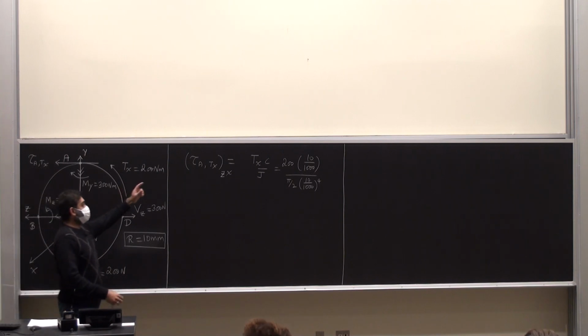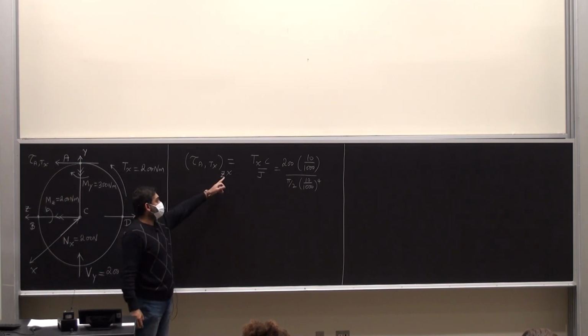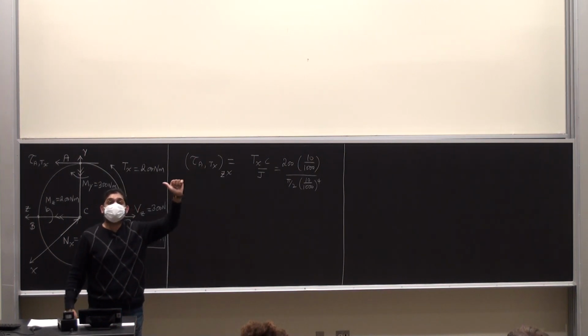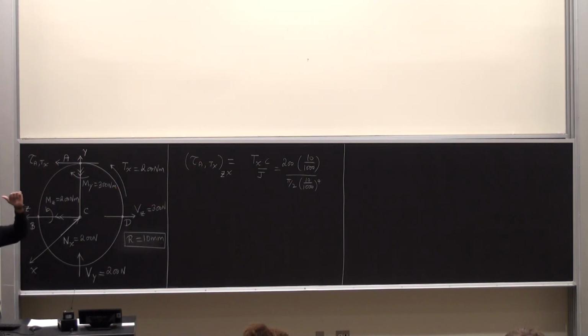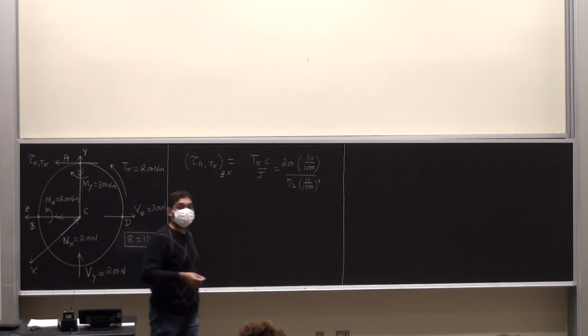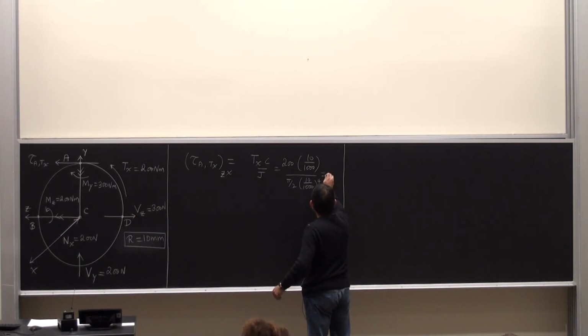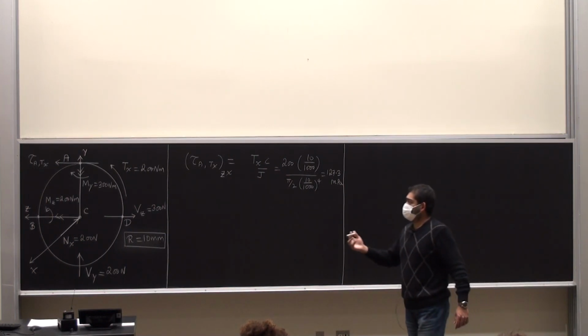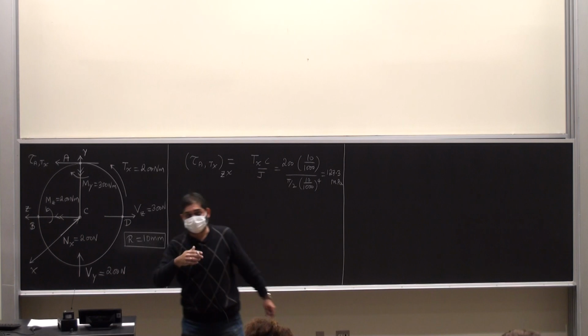The thing that I wanted to point out last time was that even when I write it as zx, just writing this out does not tell me what the direction of the shear stress is. Is it to the left or is it to the right? That is going to come from the drawing of the volume element. Alright, so if you do the computations, this ended up being approximately 127 megapascals, 127.3 megapascals.